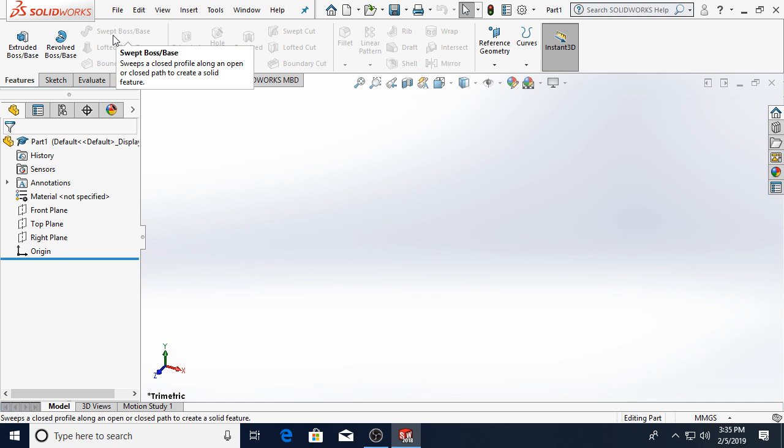When you're creating sweeps, the important things to keep in mind are, 1, Solidworks gets a little bit finicky if your sweep intersects itself. So in this case, you couldn't use a sweep if that radius of the corner was smaller than the radius of the handle itself. I mean, if you can imagine trying to figure out how to manipulate that sketch so that it swept through itself as it was going around a corner. If it was too tight a corner, it would overlap itself, and Solidworks just bails at that point.